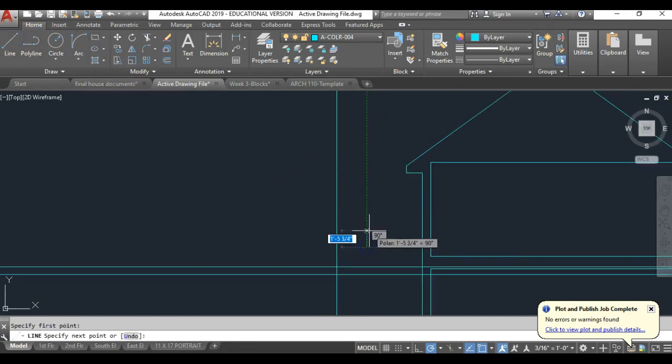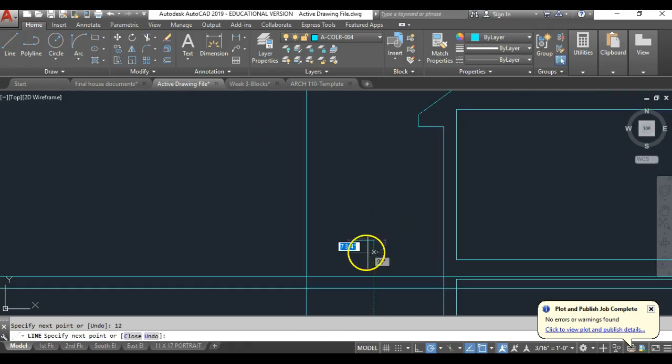So I'm going to go up 3/12, draw the angle, hit enter. I can erase the top and side of the triangle because I only need the slope. Move that whole line right over to here and extend it. Hit enter right to where it touches the building.